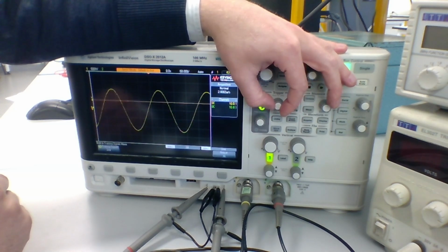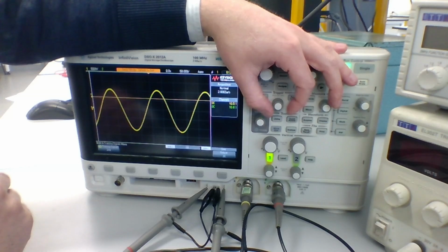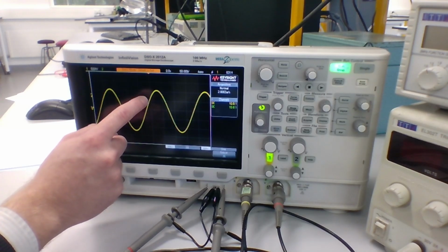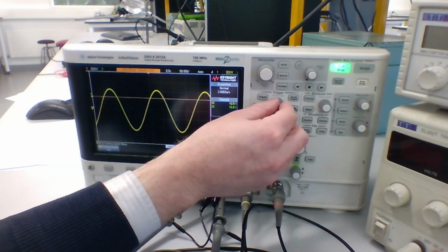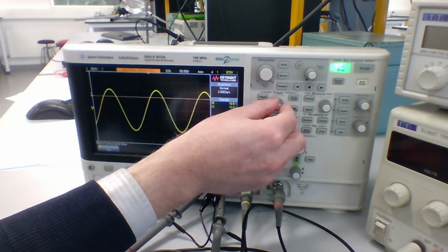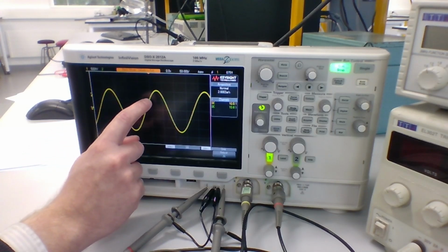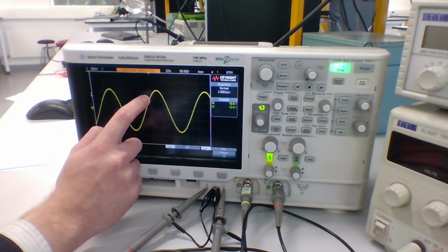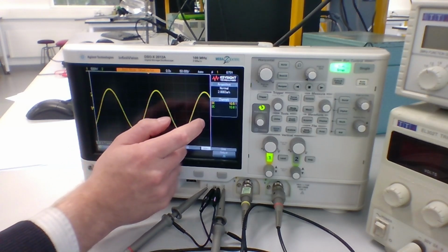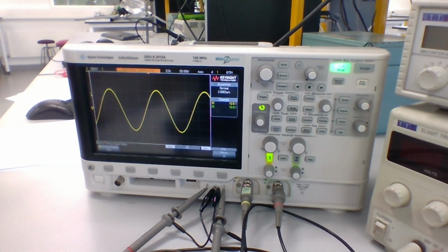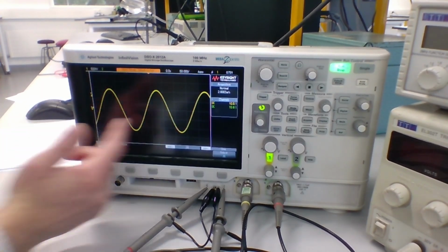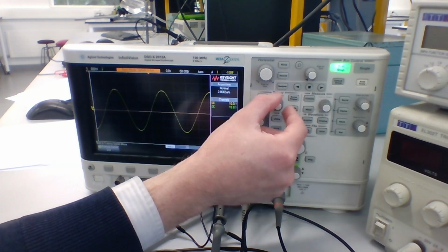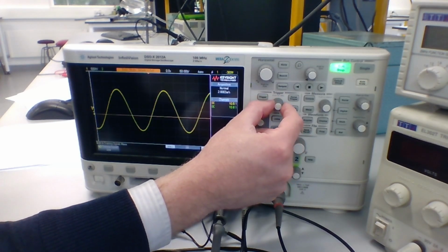As we dial this up, it is taking a measurement when the waveform of the voltage reaches the voltage of the trigger. So if I set that trigger up here at say 675 millivolts, the oscilloscope will then take a measurement when this waveform crosses 675 millivolts. That corresponds to measuring at a different point in time for a periodic signal like this, which causes it to shift on the screen. We can do the same thing. We can take a measurement at a negative voltage as well if we want to.